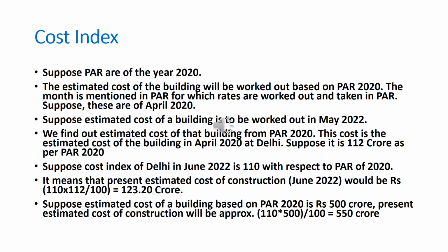Suppose plinth area rates are of the year 2020, then the estimated cost of any structure or the building will be worked out based on plinth area rates of 2020. If suppose they are of April 2020, then the rates will be of April 2020. It means month is also mentioned in plinth area rates, for which rates are worked out and considered.